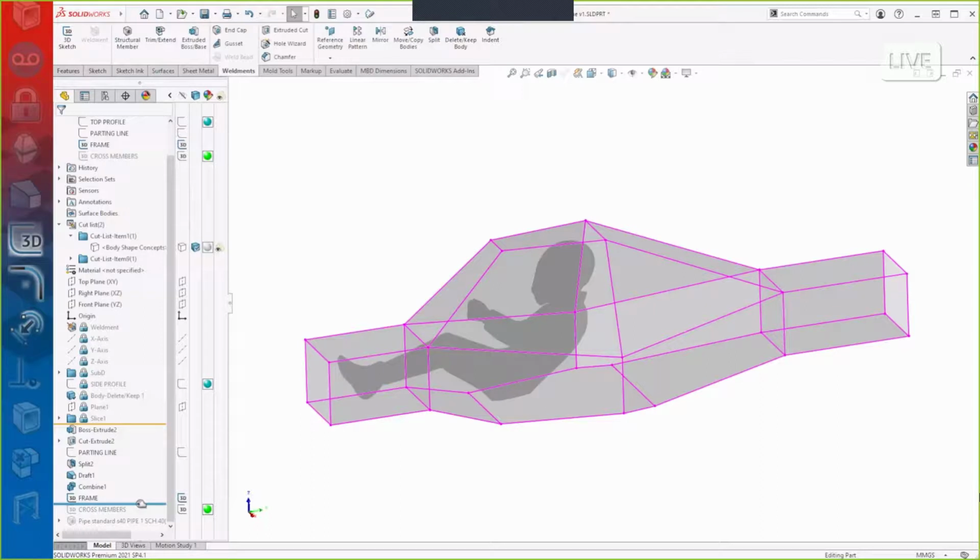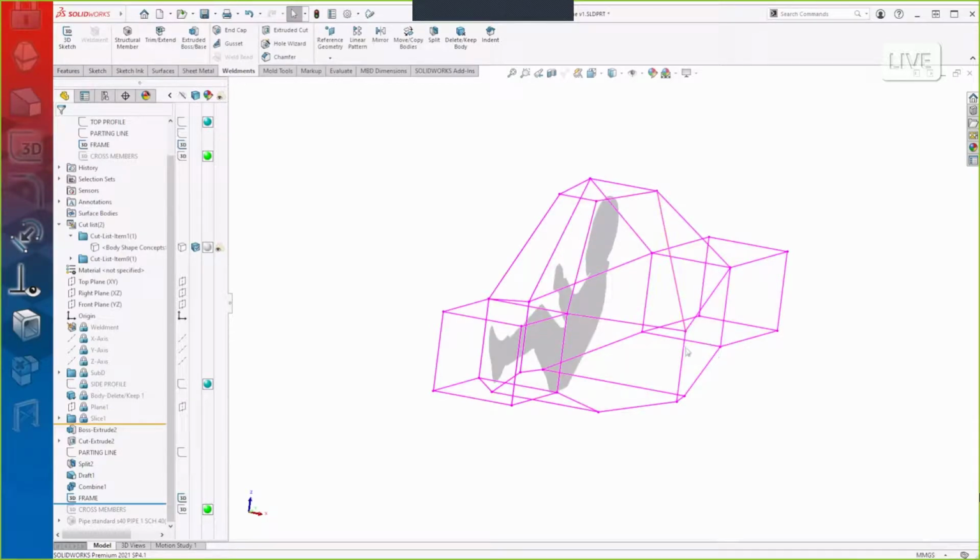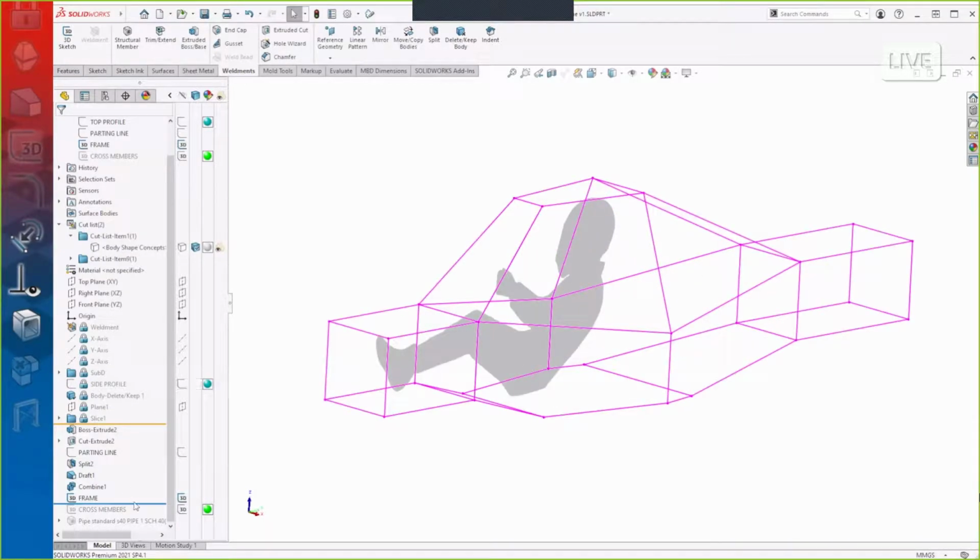I don't want to waste time sketching. You just added a fillet in a 3D sketch, and then you move this line. You use replace entities to move that line so that the weldment stays connected. Yes, that's what I was wondering. Is it going to lose that edge? What happens? There's a replace entities command highlighted right now. Yep. Okay. The other thing that we needed to do was to draft the bottom side. Shoot. Okay. So that's before the combine feature.